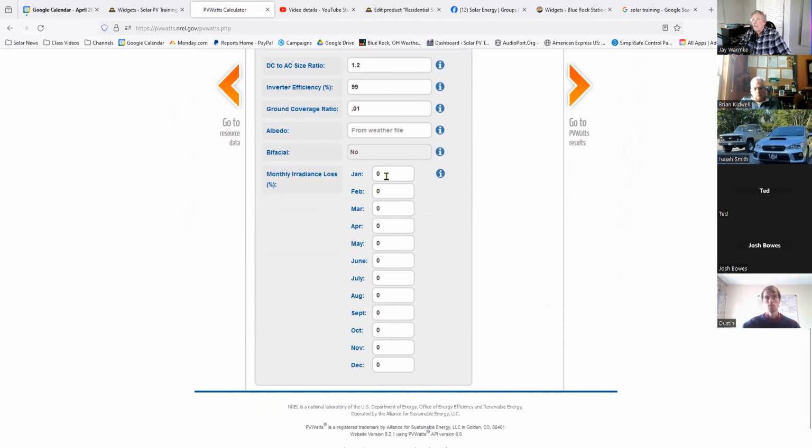and that'll help adjust it, because you remember you've got to have sort of a worst case month. This is always going to be basing the array size on averages, on annualized averages. But with a standalone system, you've got to have the worst month of production paired off with the consumption.